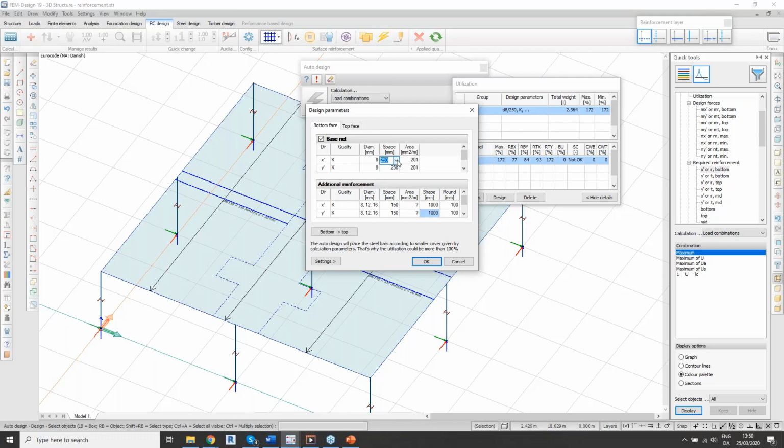of doing that. So trying to check how much you need as a minimum reinforcement, you can do that in detailed results, or you can just check in required reinforcement which kind of reinforcement is repeated a lot of times. Then you will know that that's the minimum reinforcement.